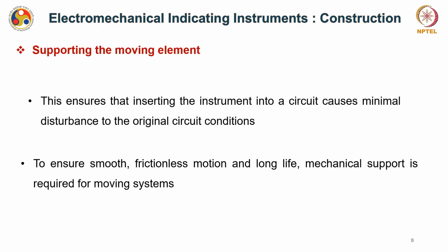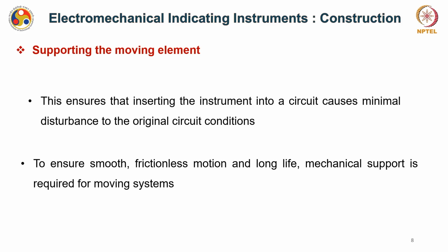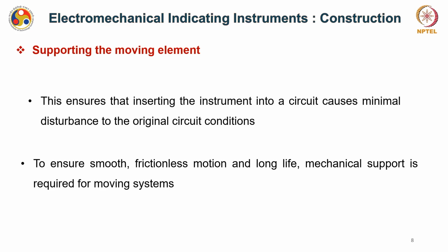Okay. So this small power also ensures that inserting the instrument into an external circuit does not cause any disturbance to the actual circuit. They are designed in such a way because ultimately the aim of all these instruments is to measure, say, flowing current, or dropped potential across a certain resistance, or a resistance value, or a certain impedance value. Okay. So the idea is to keep this as small as possible, to ensure that when you connect it in a circuit in series or parallel, irrespective of that, the disturbance caused is minimal to the original condition of the circuit.